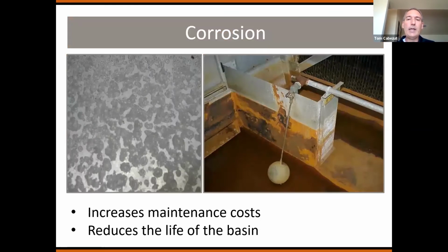Corrosion is another issue. If you can't get in there to clean out the basins, you'll end up seeing what happens when you drain a tower and the basins are left with improper filtration or no filtration and improper treatment of the cooling tower surfaces themselves. So what you want to do is make sure that we get that dirt and debris out so it doesn't just sit stagnant inside that cooling tower and rot out the basins. On average, basins last between 5 to 15 years, and I've seen some, even stainless basins, which is the picture on the left, corrode in less than 5 years with very poor water treatment and no filtration at all. So just because you have stainless basins doesn't mean that you shouldn't filter or obviously treat your water regularly.